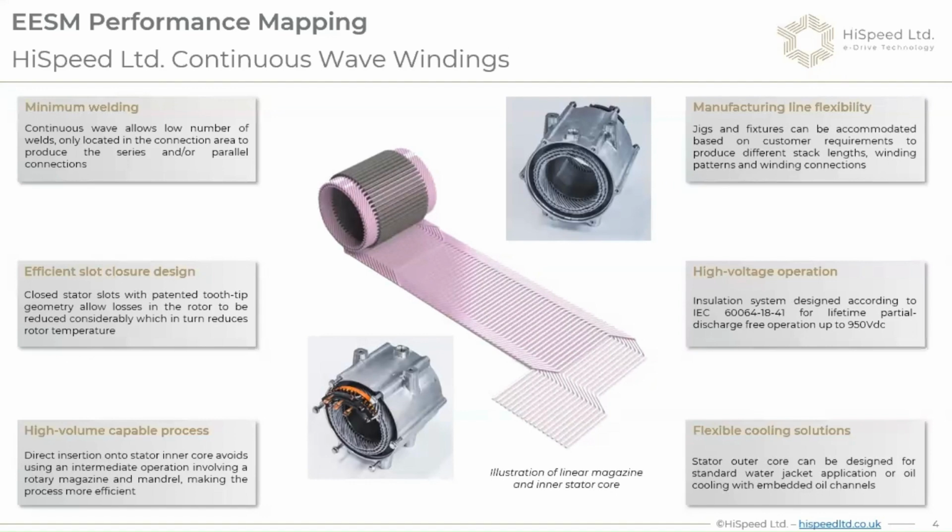And this, we believe, has significant improvements compared to the standard process, where usually the continuous wave winding is rolled around a mandrel and then expanded into the teeth, which requires open slots topologies, and these open slot topologies usually have induced quite high losses in the rotors.